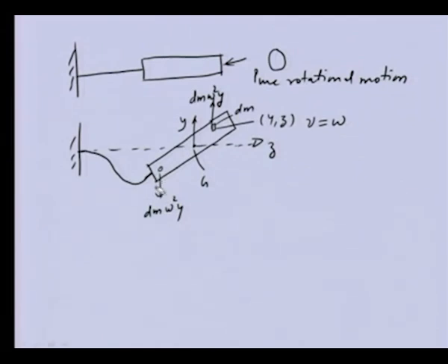Now we can see that these two centrifugal forces are making a couple, and the couple direction is counterclockwise in this particular figure. So, we can see the tilting of the disc, which, if we draw the axis of the disc, is the tilting phi x about the x axis. That tilting is becoming more because of this particular moment.